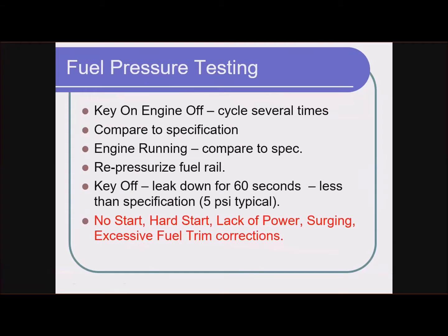As soon as you tried to go fast and it needed all that extra fuel to do it, it just wouldn't do it. At first, I thought maybe we had a plugged catalytic converter because we have talked about that. But that wasn't the problem. The problem was there was actually a leak inside the fuel tank.